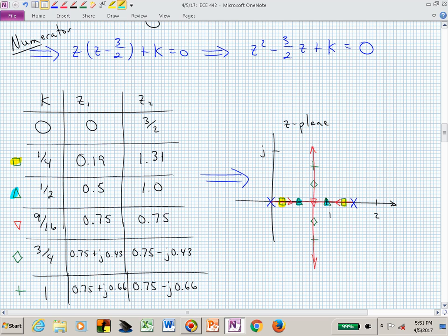That's going to be based on the pole zero excess. How many more poles do I have than zeros? Now they have to move off of the real line. And since there's no more real axis segment that belongs to the root locus, I can't come back to the real line once I've departed in this particular scenario.